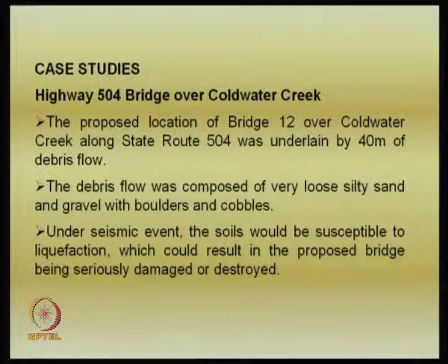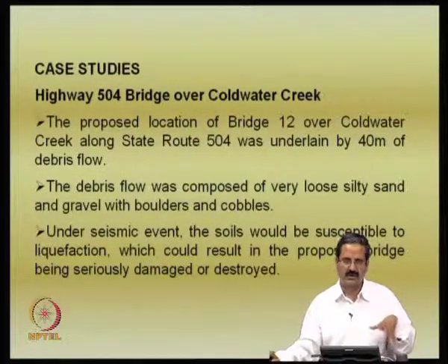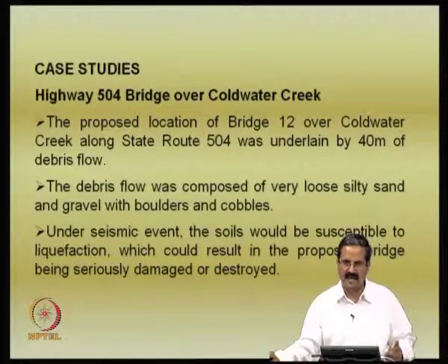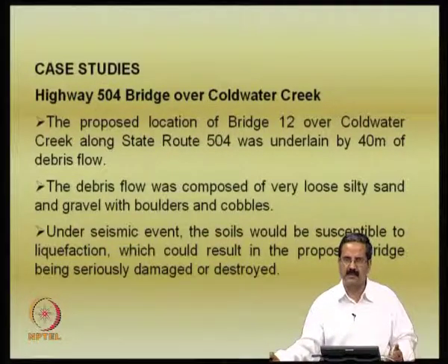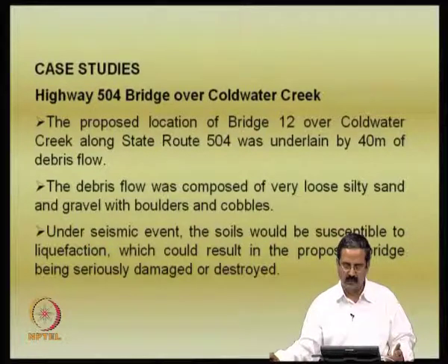There are stone columns, there are so many techniques that we did, and underwater methods and all that. So, in this case, if we are looking for a very cost effective technique, and if you can achieve it by any of these means, it is nice. You can use, for example, in a given situation, a dynamic compaction method, or you can use densification by blasting. You can just do whichever is cheaper and convenient, right, because it needs a lot of equipment. There are many issues involved in both techniques.